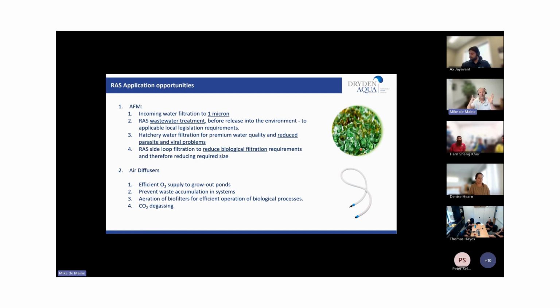So your bacterial regime is moved towards the heterotrophs rather than the autotrophs, and the autotrophs are what you want to convert your ammonia to nitrates. You don't want so many heterotrophs in your system converting the organics to ammonia first, then the autotrophs to get to nitrates, because that just needs a much larger biological surface area, right?